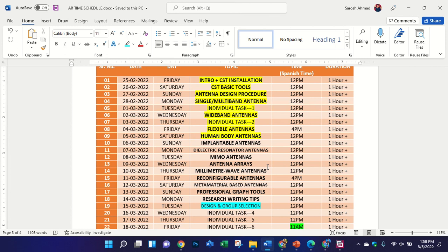People are now working on different things, as I told you, in CST and in antenna designing you are open to work. You need to find a new technique to create a MIMO. You will see many papers, people are trying to make different shapes of the MIMO to achieve novelty. Even in our case we can design different shapes of the MIMO antenna, connecting the antennas in different ways, with different antenna elements. The most important thing in MIMOs is to keep the size compact and to achieve better isolation.